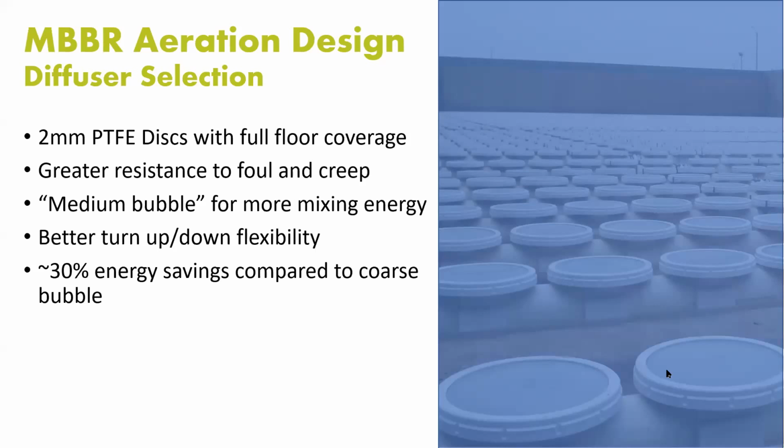Like I said, one of the downsides to fine bubble aeration in an MBBR system in the past has been the operators not wanting to drain their tanks to clean the fine bubble membranes once or twice a year. When you drain a tank, obviously the media is going to be at the bottom of the tank. It's going to make it more difficult to access the grids.